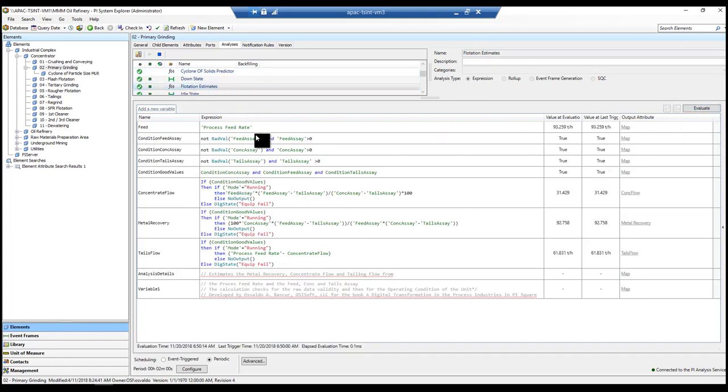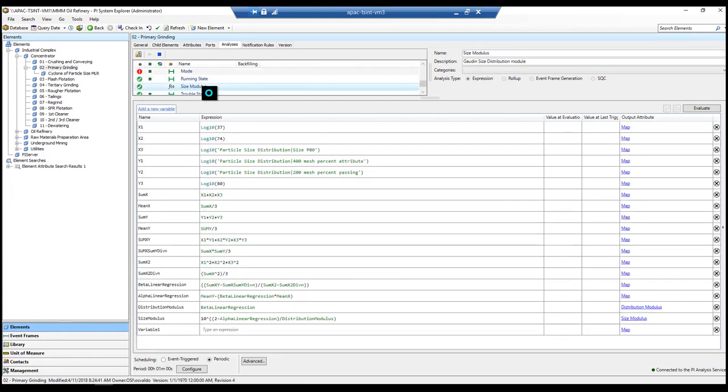Now you get the data, you validate your X-ray analysis, and then you can calculate your concentrate flow, the metal recovery, and the tail flow. By having that number, then you can relate it to your grinding and relate it to many of the other operating conditions that you're running, so you can optimize or find out what are the key elements that I need to optimize.